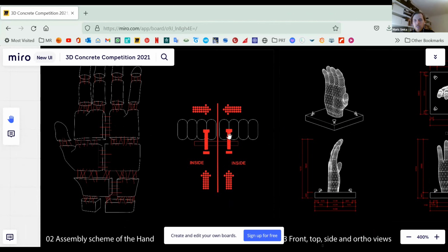Yeah, the idea was to put the screws in, and the screws we can basically get somewhere in the depot, it's not a problem. But the metal plate, the idea was once the screws are fitted inside and the concrete cures, then we can take this plate, measure, drill holes and put it on top. So we don't need to do it now, we can do it after that. That was the plan.